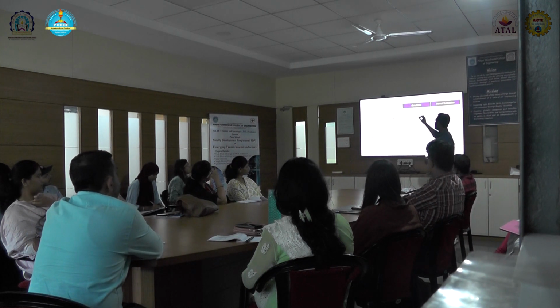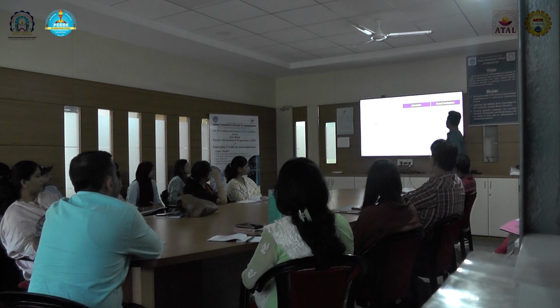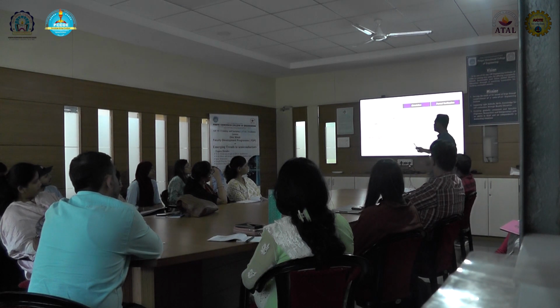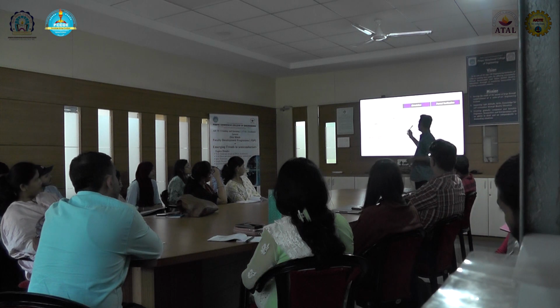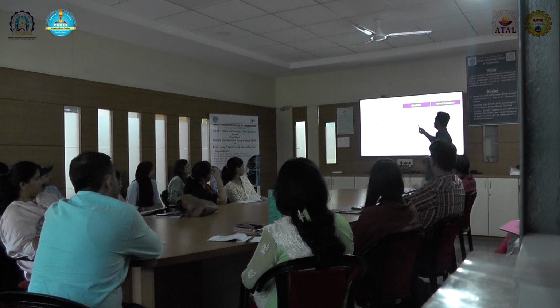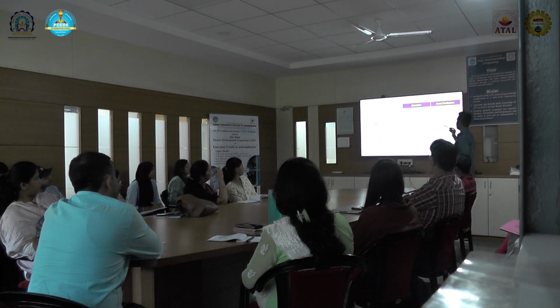In simulation, it focuses on the scenarios and it only reports if the assertion fails in the design. But in formal, the intent is focused on the behavior; it will try to falsify the assertions. You can see the setup time required to develop the test bench in simulation is very high, whereas in formal we can start early in the design.